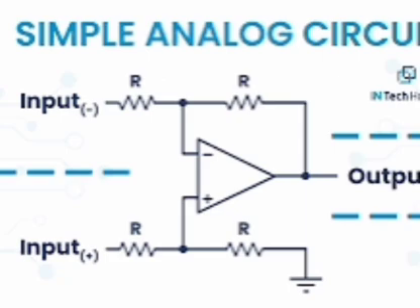BJT characteristics. A transistor is a 3-layer, 3-terminal, 2-junction semiconductor device. It consists of either 2 n-type and 1 p-type layers of material called NPN transistor, or 2 p-type and 1 n-type material called PNP transistor. In transistor, current flows due to both majority as well as minority carriers. That is why it's called a bipolar device.